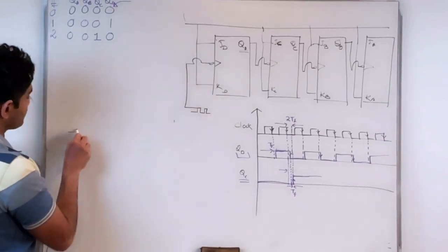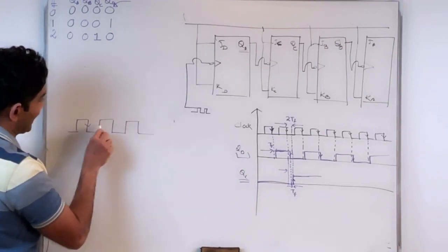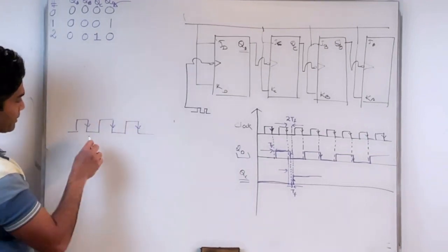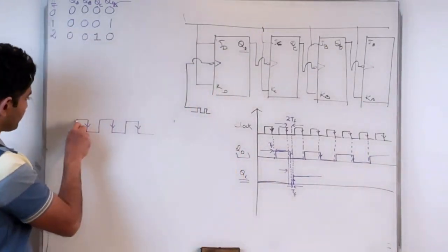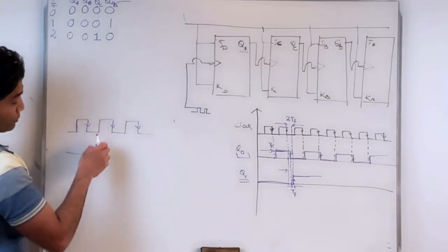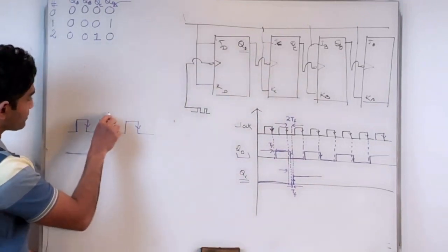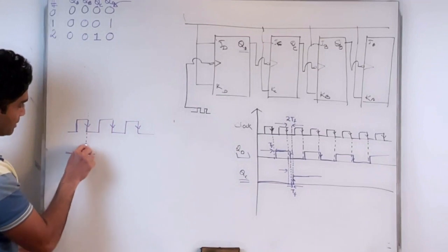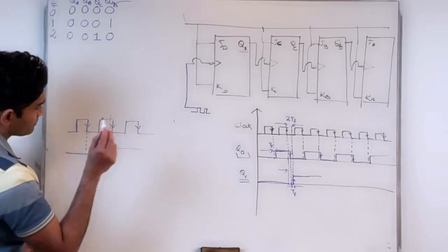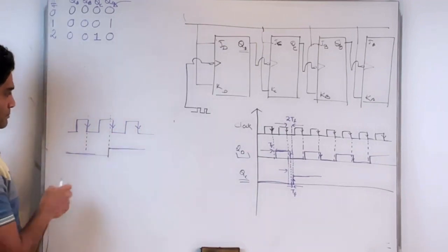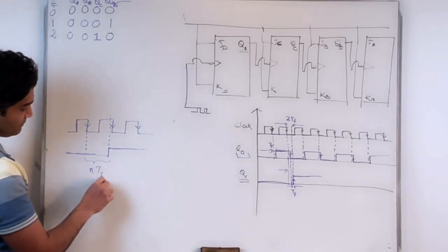Now I have this clock pulse, the master clock pulse. These are my active edges. For a particular stage, I have added n stages, and the timing delay adds up with each added stage. My flip-flop timing delay is increased so much that instead of switching here, it starts switching here. The delay has added so much. Let's say that's n times TF.